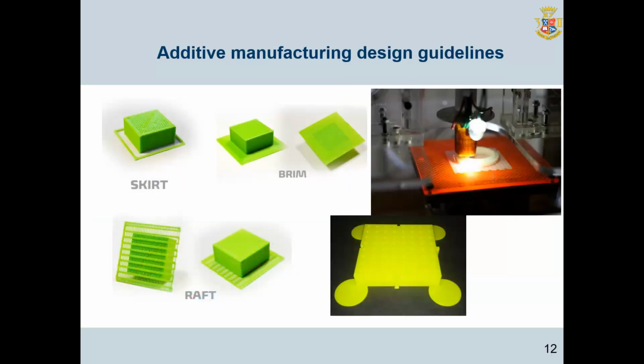The substrate is the basis of the model made in the form of a grid. Due to their high porosity, such structures cool quickly and evenly, and then serve as a reliable basis for the printed part. The larger and thicker the substrate, the stronger and more reliable it is. However, you will have to find the perfect balance between functionality and material consumption. The slide shows various options of the substrates: a skirt, a brim, a raft.